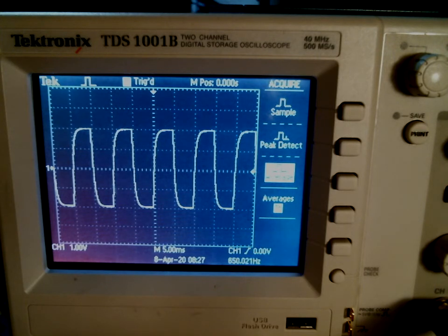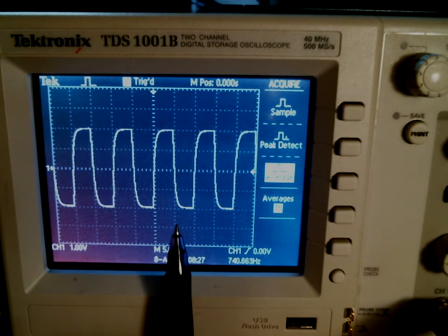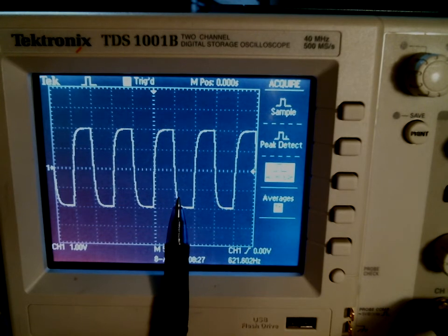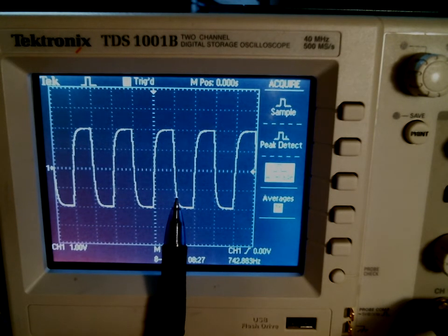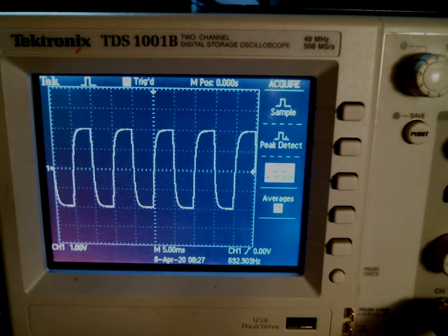So now we want to actually measure the RC time constant of this circuit, which is much shorter than the period of the sine wave generator. And the sine wave generator's data is not especially important. I'm just using it as an example of how you would measure times from this scope.